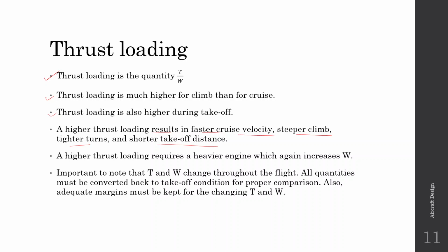So the passenger aircraft cruise at lower velocity. They cannot climb as fast as the fighter aircrafts. They cannot take tighter turns, and they require a longer runway for taking off. So a higher thrust loading requires a heavier engine, which again increases the weight.